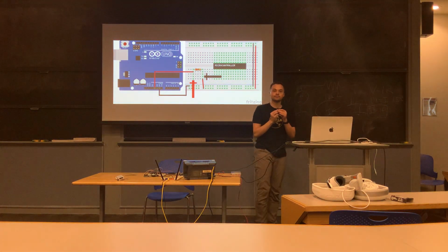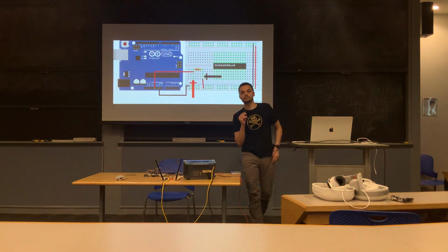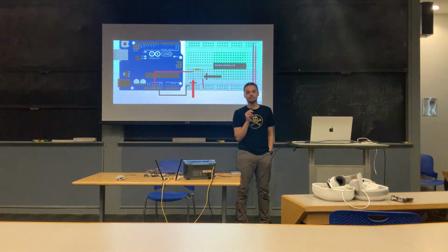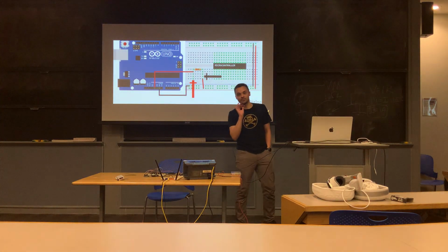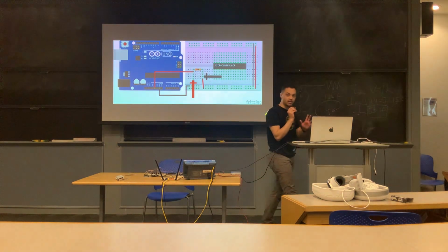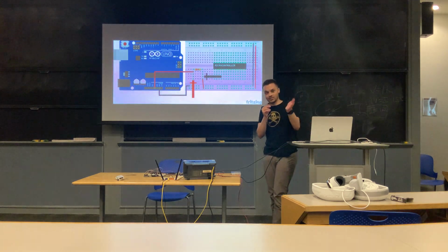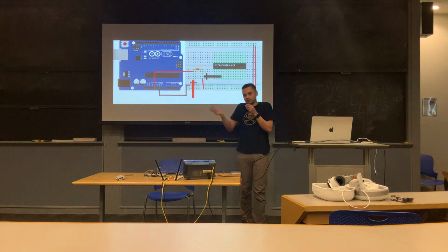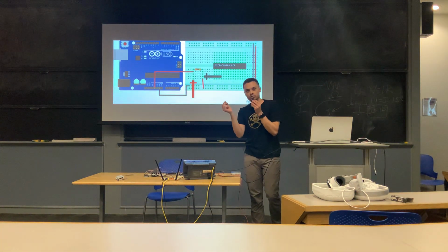If there's a voltage drop between the voltage source and the device under test, then couldn't you run into the problem where the voltage is lower for the device under test than it's expected to be, and then everything runs slower, etc., so you're not getting like the exact behavior that you would expect without the shunt resistor? That was an excellent question. What was your name, by the way? Shruti? Excellent question. So the question was, what happens if you have a shunt resistor? Yeah, you're going to have some voltage drop between the source and the device. So the answer here is, for us, it doesn't really matter. It still is able to work. You want to select your shunt resistor so it's a very small resistance, so it's not a huge voltage drop.